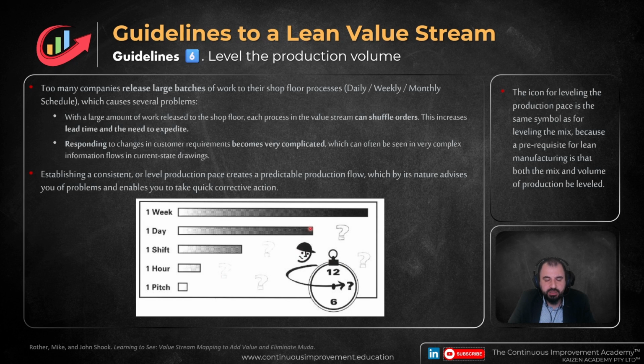And we also have another principle, which is leveling the production volume. So the previous one was leveling the production mix. This is talking about the production volume. And basically it means instead of releasing large batches of work to the shop floor, which would create kind of chaos because takt time is not linked to what you schedule, and the uneven workload and difficulty to monitor and increased lead time.